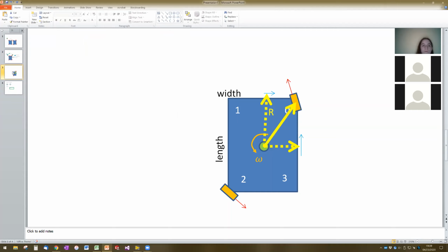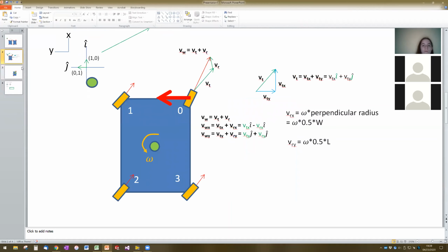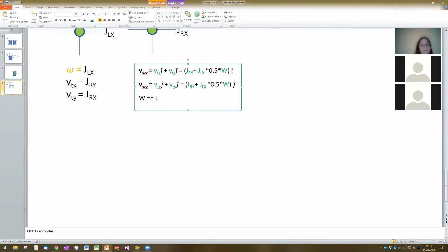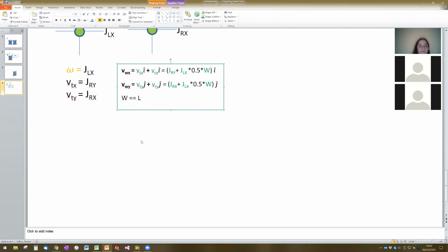So, okay, that describes everything about how we get from the joysticks to these velocity vectors. Now, we still have the challenge of taking the velocity vectors, which is how we describe everything in math really conveniently, and converting them into an azimuth angle for the swerve module, and into the actual speed that we should be spinning the wheel at. So we've got to do one more set of steps, a conversion. We're looking for an azimuth angle and a velocity magnitude.